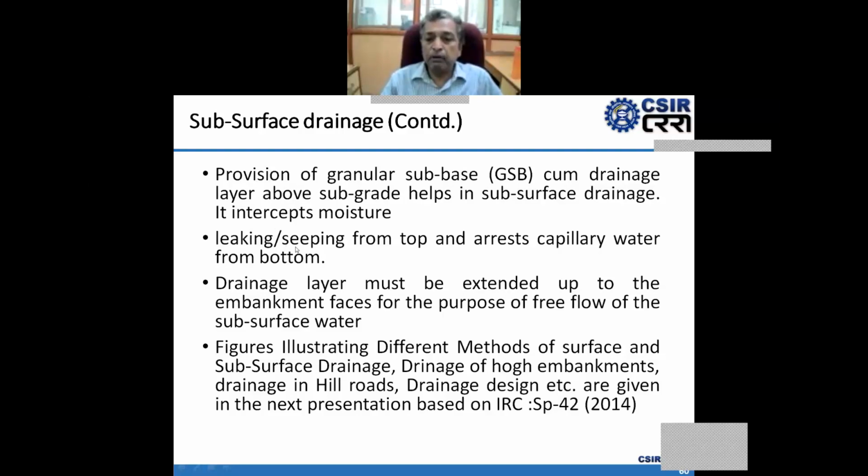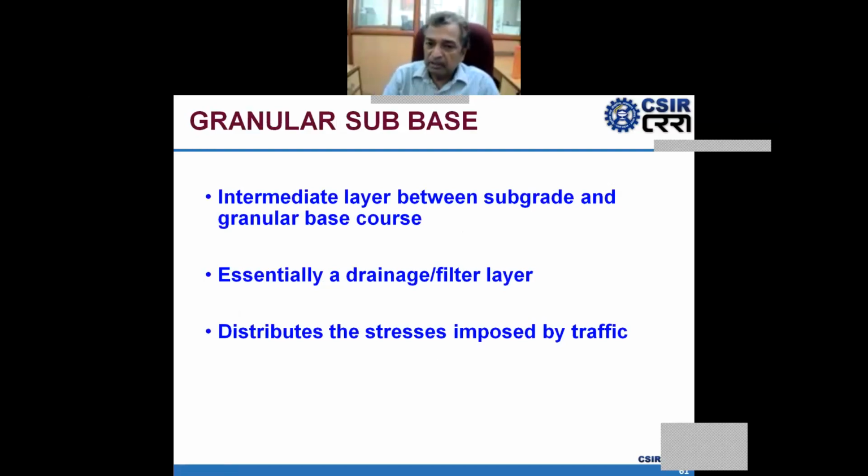Leaking, seeping from the top, and arrest capillary water from the bottom. The drainage layer must be extended up to the embankment faces for the purpose of free flow of the subsurface water. So a granular subbase layer should be provided as a subsurface drainage. It should be an intermediate layer between the subgrade and the granular subbase.